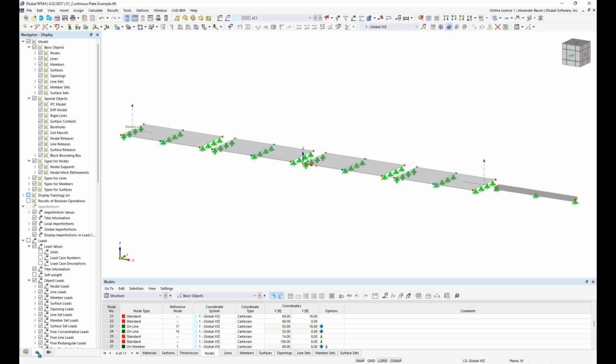Next, we have the display tab down here at the bottom. Under the display tab, you can turn on or off the graphical rendering of objects and other settings. Turning off and on the render of something just turns off the rendering, and it will still be considered within the calculation even though you can't see it in the work window.